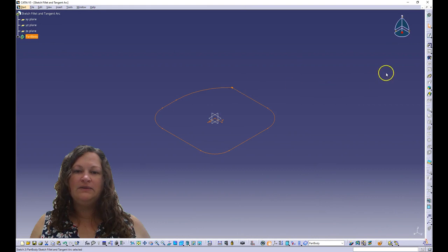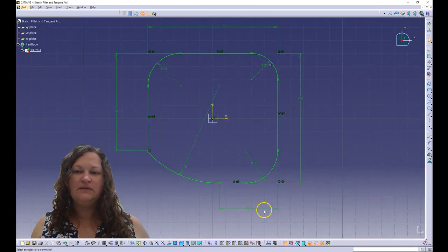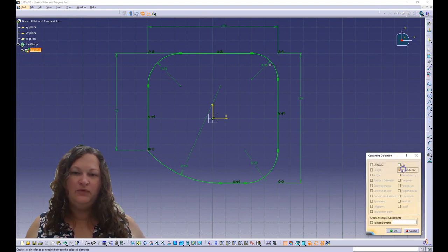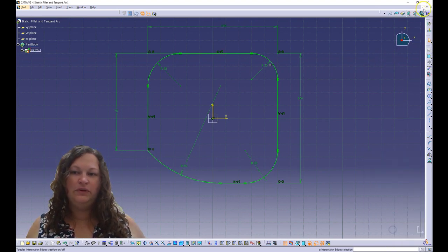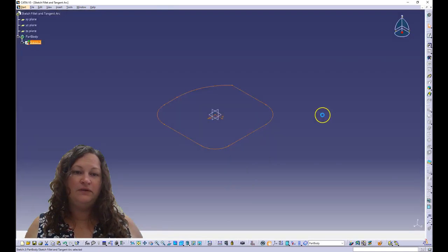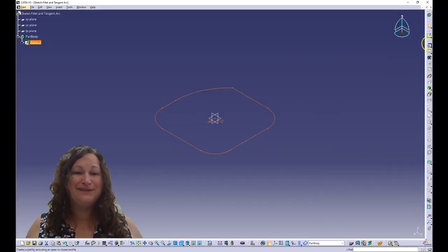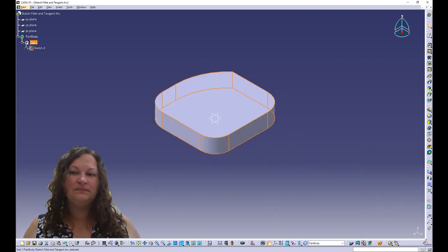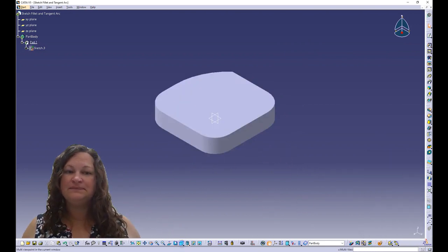So when I go back into the sketch, I can eliminate that last horizontal length that I added. And then from there, it'll allow me to make that endpoint coincident with the line's endpoint. And that also fully constrains the sketch, but this time as a closed loop so that I can pad it. But that's it for sketch fillets.